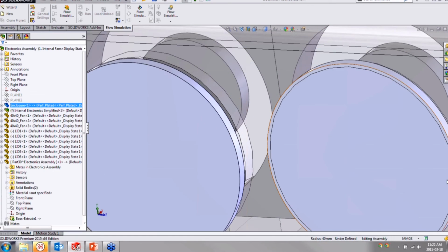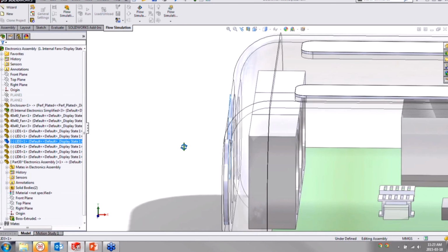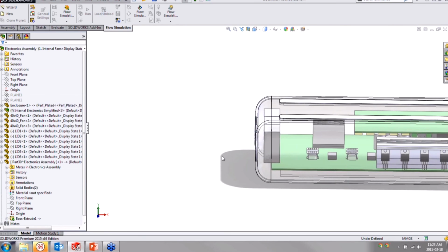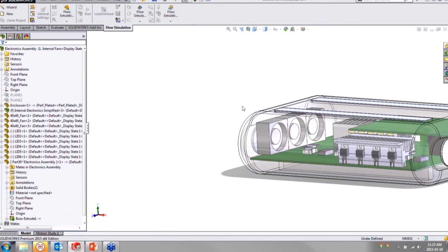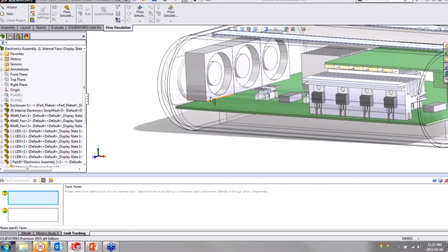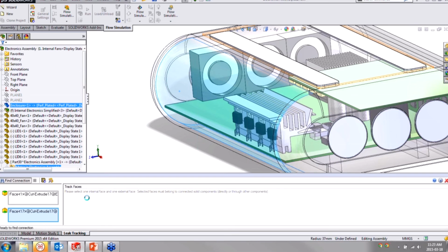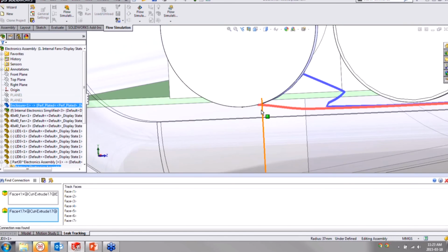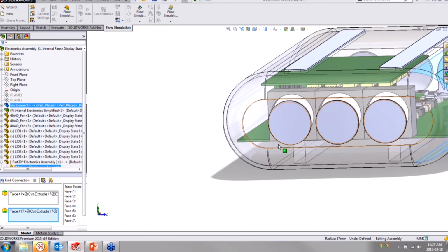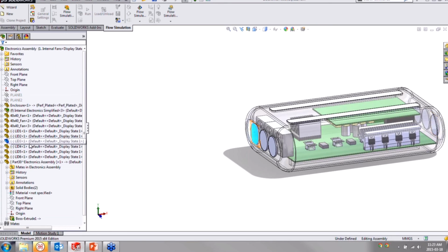And so I'll close up leak tracking. I need to fix this lid. I'd probably model it manually, but for now, let's just drag it back into place. I think that looks good. We can double check it by running that leak tracking tool again. Looks like it's still open, so there's a little gap at the bottom here. I can go through and try to fix that again. And maybe at this point, it might be easier if I simply get rid of that lid altogether. Let's just delete that, and let's do it manually.